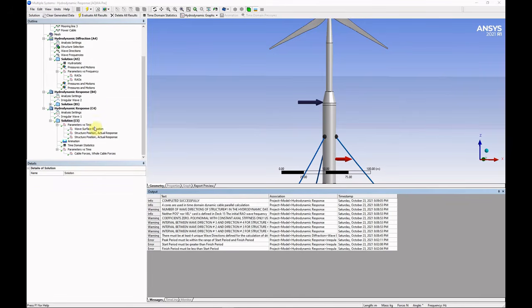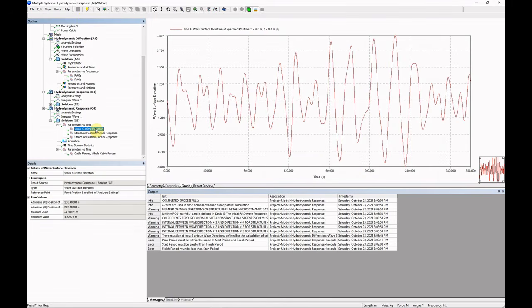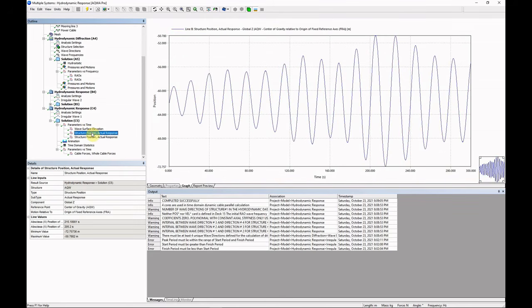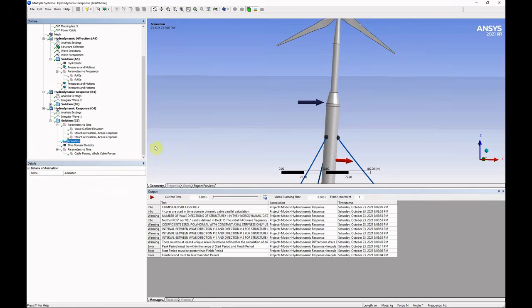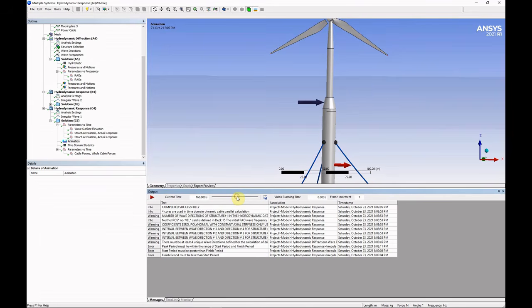We can confirm wave height is now much bigger and at least one wave with about 10 meters of amplitude happened at around 200 seconds time. Platform heave motion looks in resonance and is moving more than the waves, with about 20 meter total heave amplitude. Pitch inclination has also increased and about 9 degrees plus and minus is occurring after 200 seconds. The animation at exactly 200 seconds will show a large motion for this heavy storm condition.